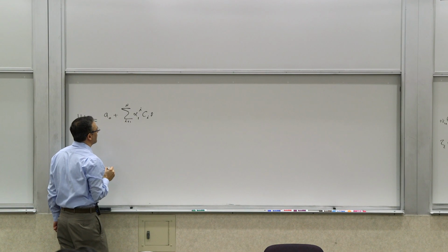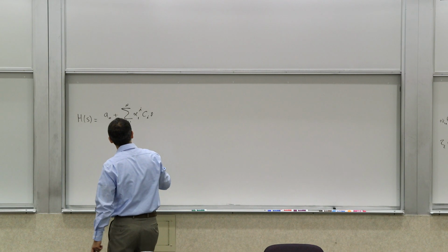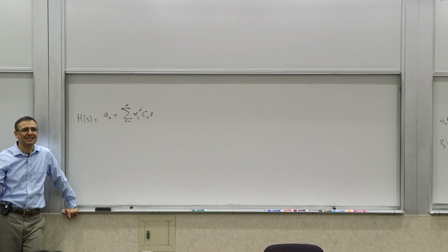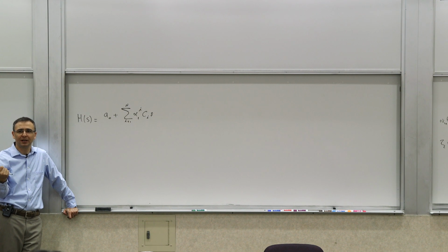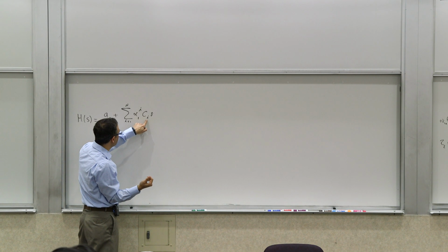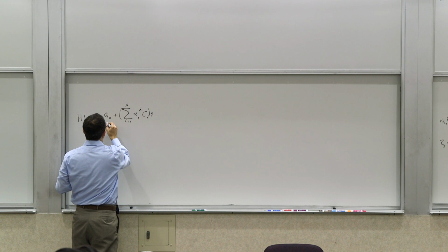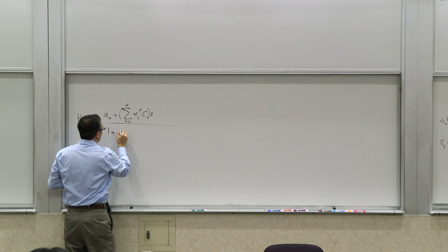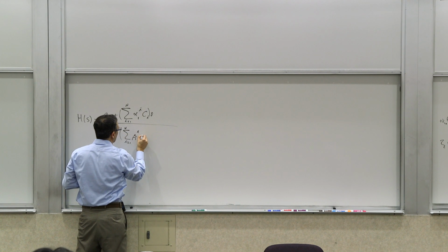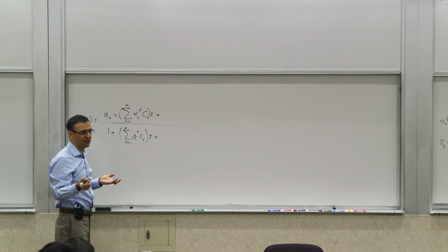alpha 1i times Ci s. So we argued that the first order terms come from products of capacitors and inductors, because the only way you get an s, a complex frequency, is either through a Cs or an Ls in your transfer function. So the first order terms have to be linear combinations. If you factor the s out, this is your a1. And similarly b1 has to be a linear combination of the capacitors. So this was your a1 and b1, and we did this derivation before.